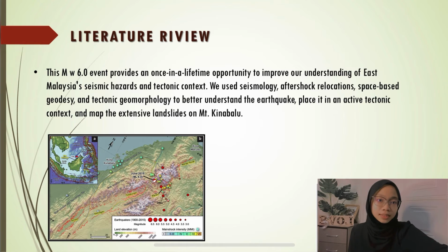So, the Mount Kinabalu MW 6.0 event provides a once-in-a-lifetime opportunity to improve our understanding of East Malaysia's seismic hazards and tectonic context. We use seismology aftershock relocation, space-based geodesy, and tectonic geomorphology to better understand the earthquake, place it in active tectonic context, and map the extensive landslide of Mount Kinabalu.